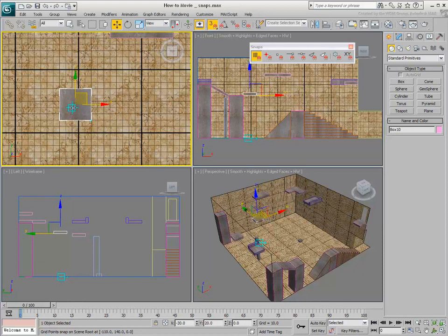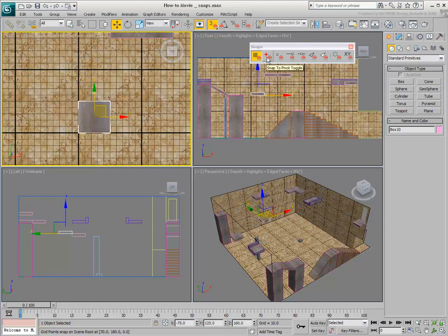The texture map in this example has been set to match the existing construction grid. Perhaps more importantly, you can snap onto geometry points such as objects' pivot points, vertex points, midpoints, edges, faces, and so on. Arguably one of the most valuable snap options is vertex, which lets you snap onto any intersecting point between two or more edges.